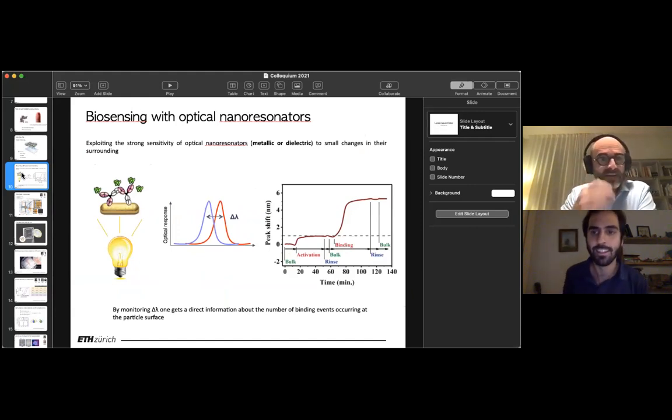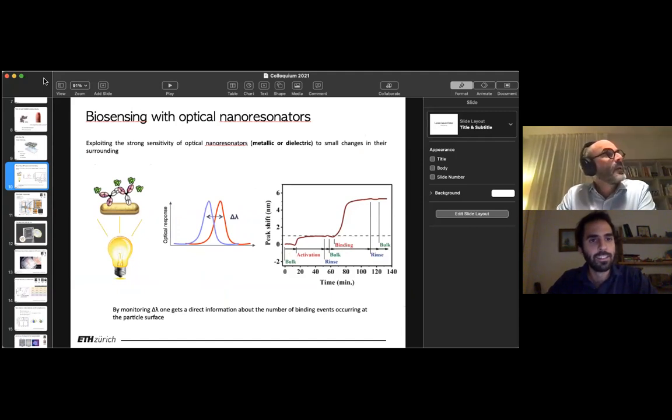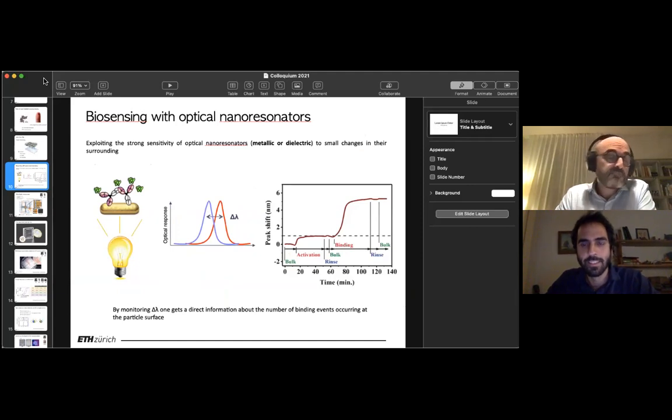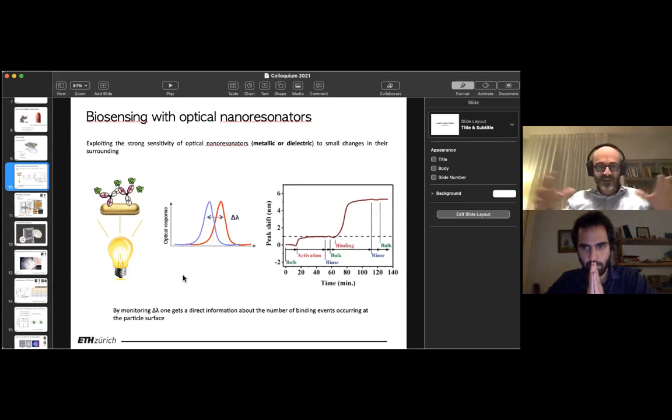Yeah, this is a very good question. Actually, there are some rather recent implementations of single-molecule binding events detected with these resonators. Here the challenges are the following. I've mentioned before that these are very lossy resonators, which means the optical quality factor is quite small. If I said the figure, people from cavity physics would laugh at me, because it's typically a few, basically 10. So 10 would be the quality factor.